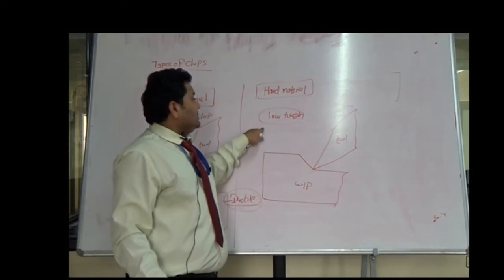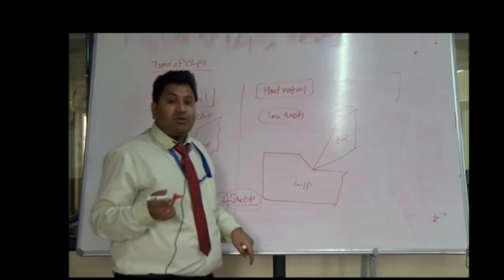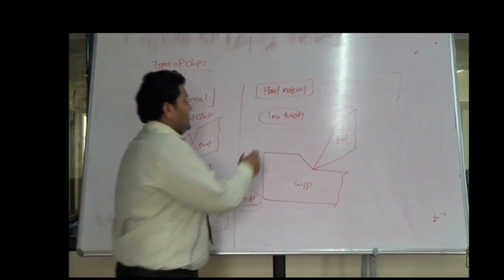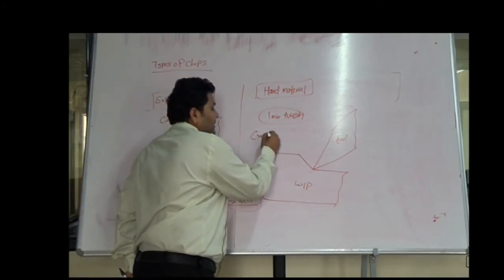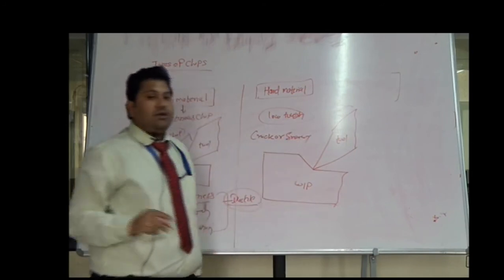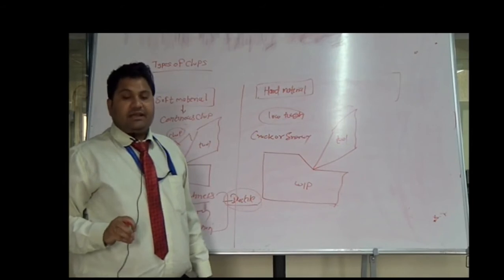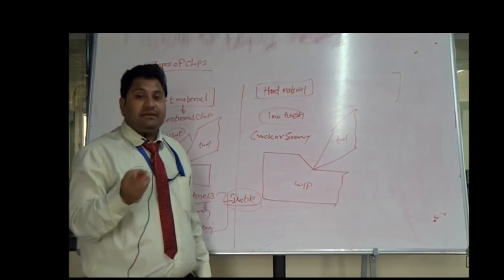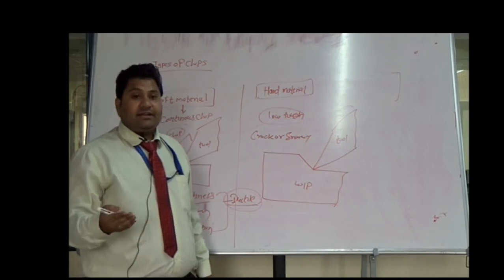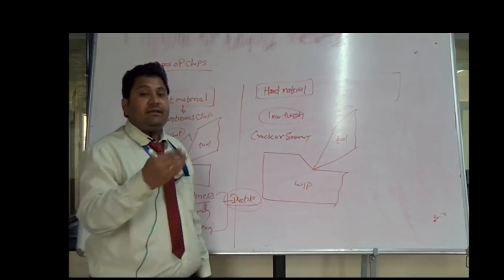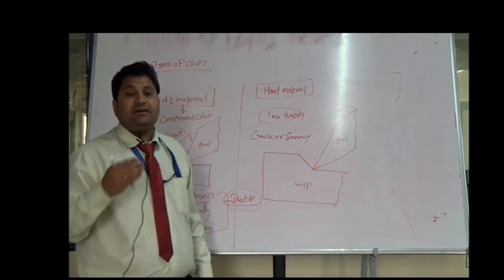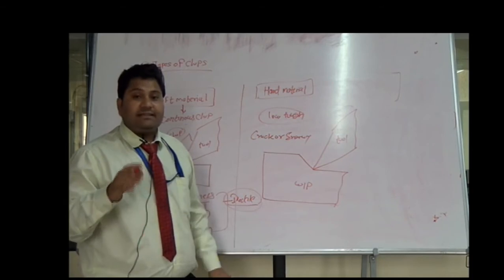We take the low toughness. Because of this property, the crack wave or energy wave is not absorbed by the material. It does not disappear in the middle portion. So the material is cut, or machining takes place, in a discontinuous manner, meaning the chip will be formed step by step.